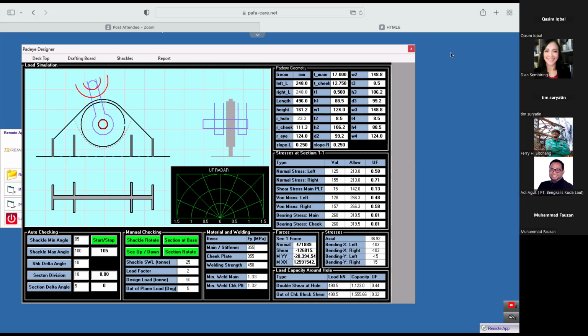So the main plate welding to the object is good enough to resist the force, but as you know, of course, the bracket needs to be welded to attach to the main plate. So basically, a minimum fillet weld of the bracket or the stiffener to the main plate should be adequate. There's a standard, for example, a quarter of an inch welding should be practical, or half an inch should be practical. So basically, that's my answer.